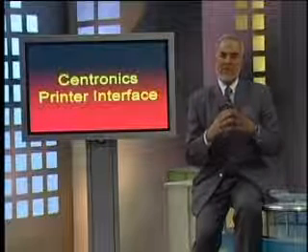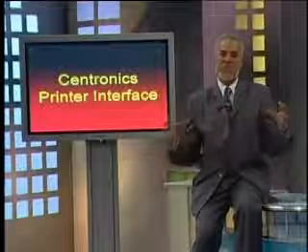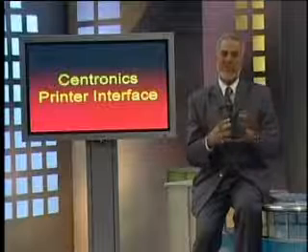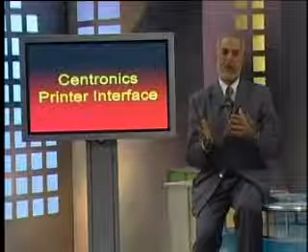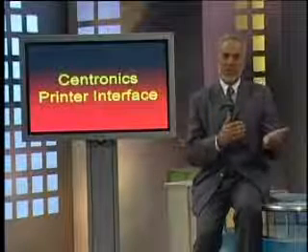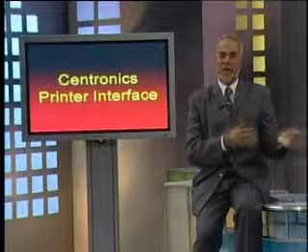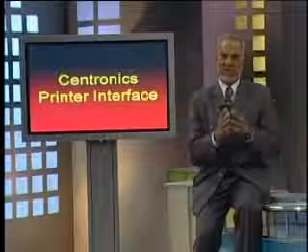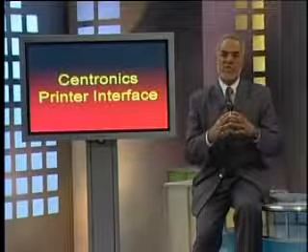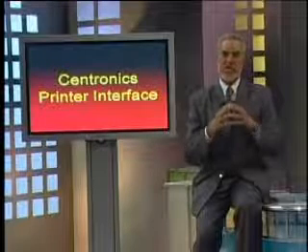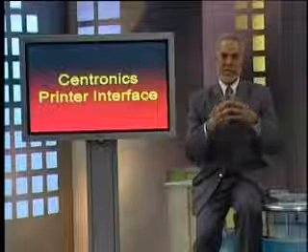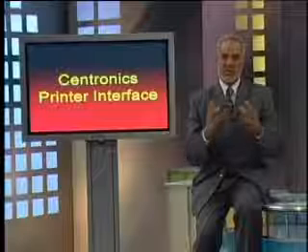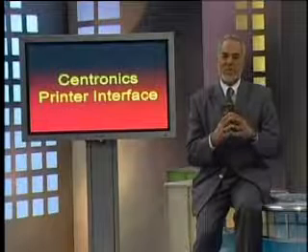Now, the fourth register would not be used in this case because it is actually a link where unidirectional data would usually be transferred. That means the data would come from CPU towards the printer, and no data would be sent from the printer to the CPU except for the status signal, and for that we have provided a status register. So therefore, three registers are provided: a data register, a control register, and a status register. Each register is 16-bit wide.